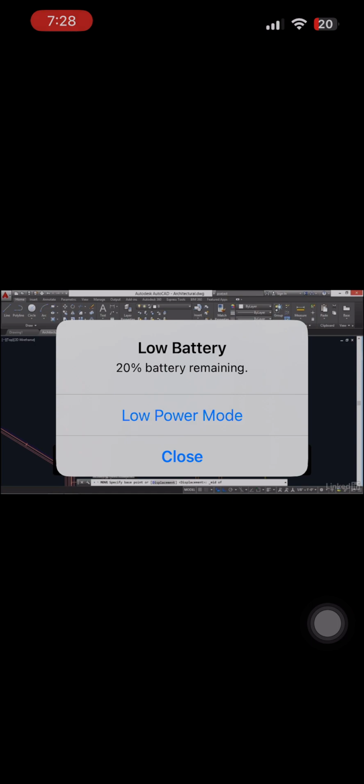And then if I move the cursor close here, you'll see this green triangle symbol appear. This would be good for any midpoint of any object. In this case, I want the base point to be right here, so I'm going to click while that green symbol is shown. I'll turn off ortho by pressing the F8 key. And now it says specify second point. So this is really the point B. It's where I want to move the chair to. I'd like to move it right here at the midpoint of this coffee table.